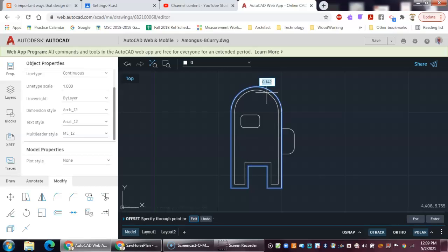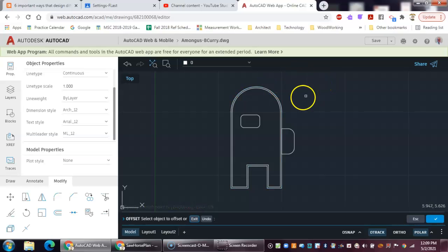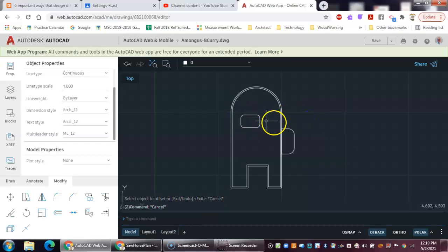And I'm going to offset this 0.05, 50 thousandths of an inch. All right. I want two more offsets here. So I'm going to right click. So, I'm still in the offset tool, so I don't have to do that. We'll cancel that out. It releases me from that command, but I'll show you in the next one.